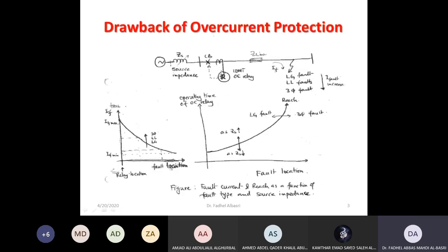Okay. So in overcurrent relay principles, if I have a relay here at the beginning of the line, we know that its operating time depends on the current magnitude. It's inversely proportional, right? As current increases, the time decreases. Now, this is if I use IDMT characteristics. Okay, standard inverse, very inverse, they all operate in this inverse relationship. Now, that makes the relay,